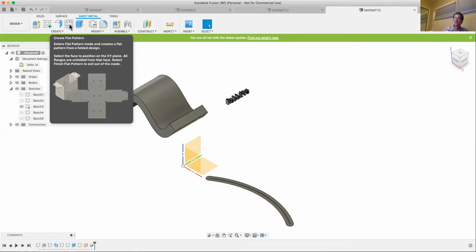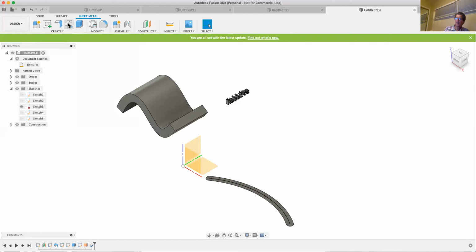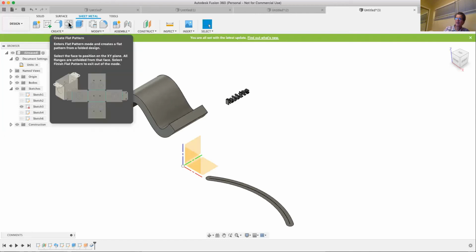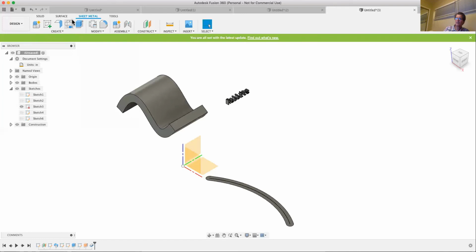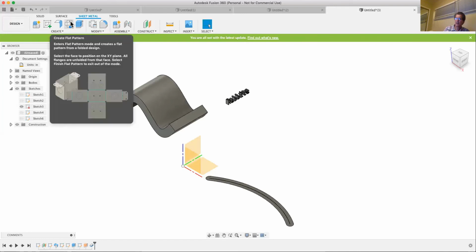So here's an example. If you mouse over it, you'll see a junction box. And the junction box has a number of really cool features on it. It has mounting flanges. It has the shaped box itself. And it has what we call half shears, where you would punch out a cable entry. Well, you can design all that in 3D using sheet metal functions, and then flat pattern. And on the right of the pop-up, you'll see what the flat pattern would look like.